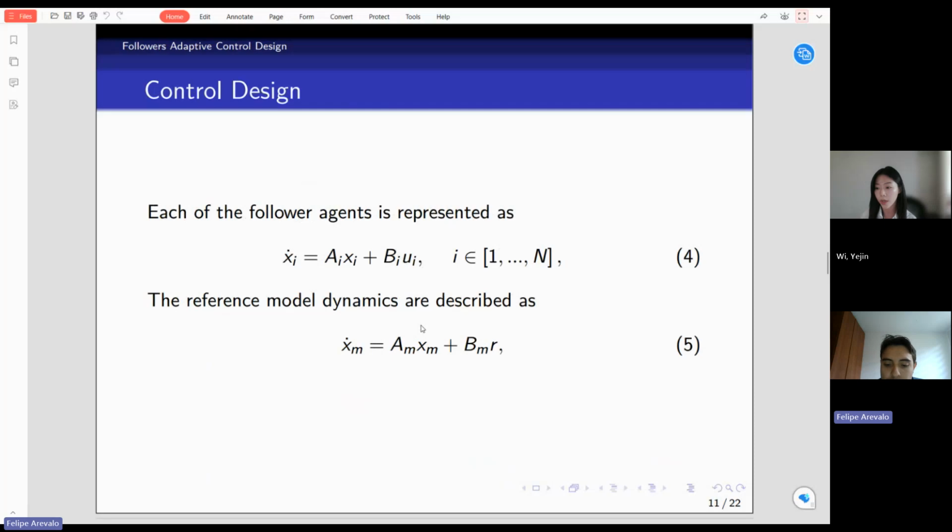So with the information of the leader-follower configurations that we're proposing, we considered, given the effectiveness of the PID controller, using it as the controller for the leader configuration. For the followers, we define a model reference adaptive control that is going to be used with the communications that all the drones in this case can have.